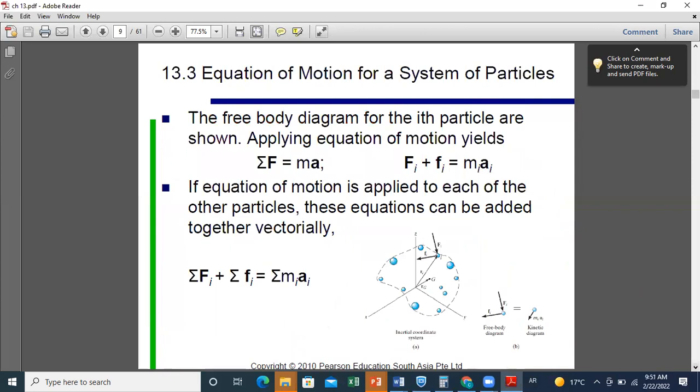Now, what is the equation of motion whenever we talk in an absolute frame? The equation of motion is the sum of external forces equals ma. In case the frame is non-inertial, we should add the inertia force to the balance of forces. This is the only difference. So if we consider the case of sum of forces equal ma, we have the following.